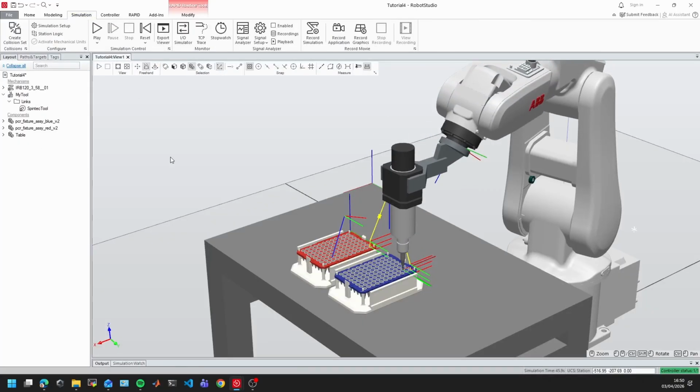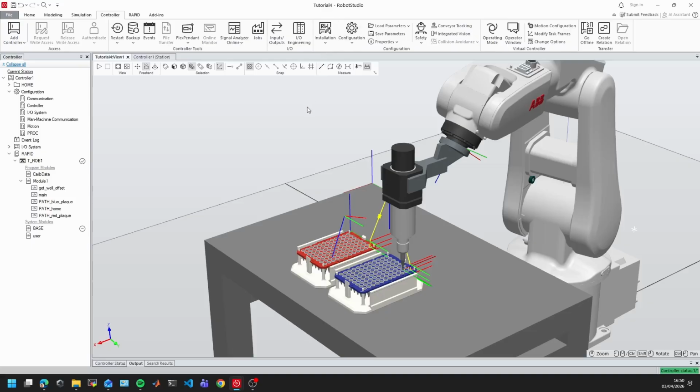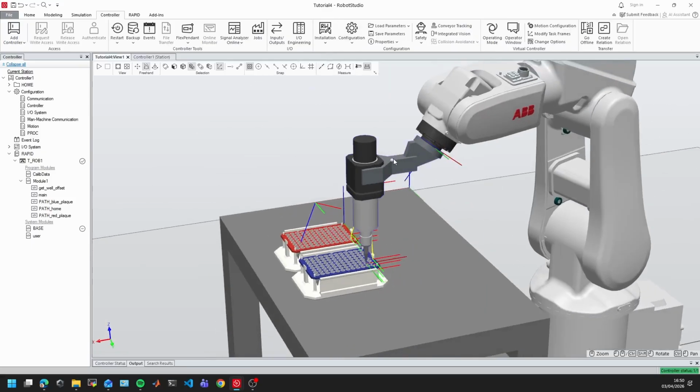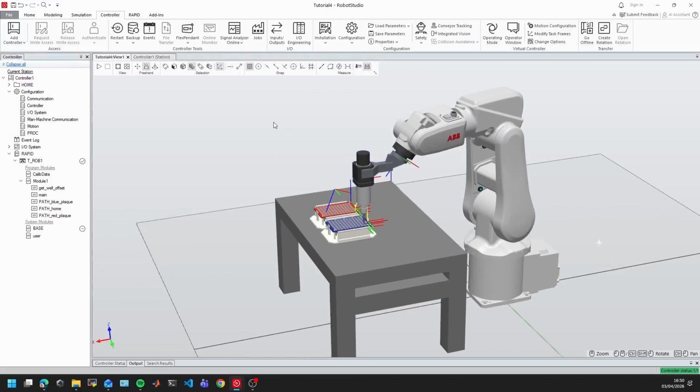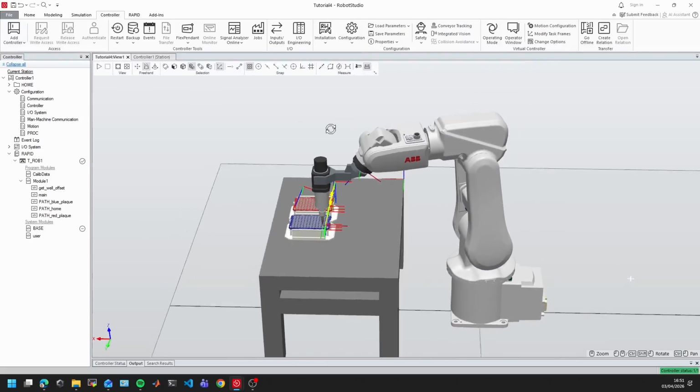So in today's lesson, as stated before, we're gonna start making some inputs into our controller, because we don't see it in here, but this robot is connected to our controller, and in the controller you have inputs and outputs, or you can actually connect some communication devices. Like if we remember from the previous tutorial, we connected a Profibus device, to allow us to connect to other devices. So we can simulate that in here as well.